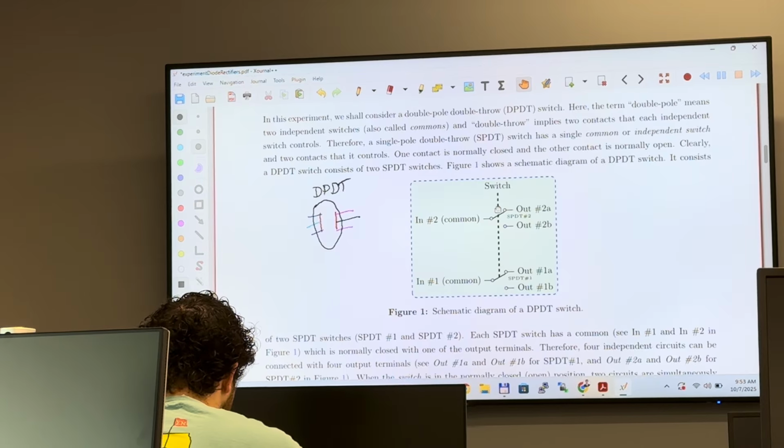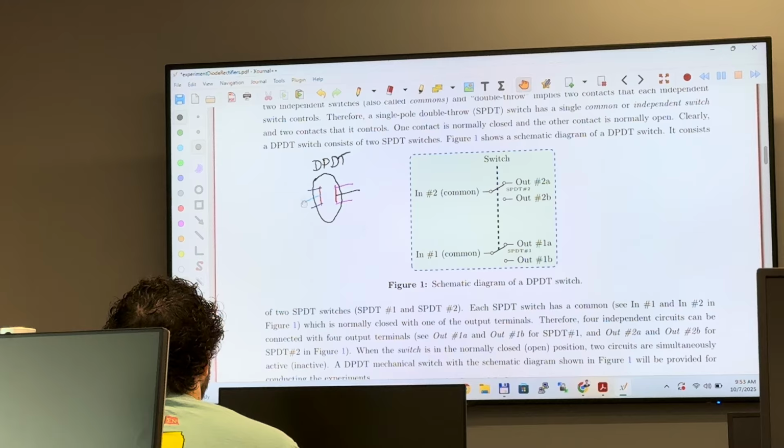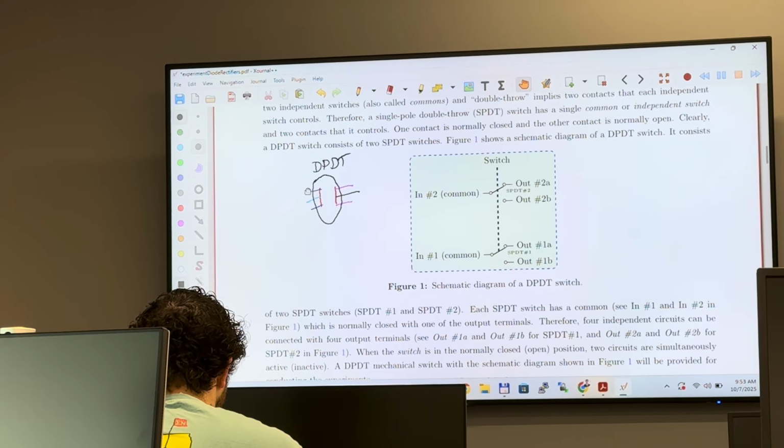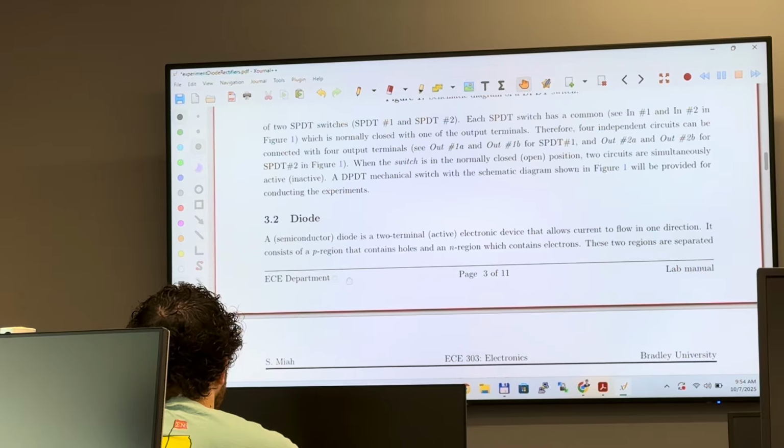You see that? And that's the internal structure of this mechanical switch. So for this side, again, if you have the switch in one direction, this terminal is connected to this wire, or if you switch in the other direction, this wiper is connected to that wire. So it is a double pole, double throw switch, the switch that you'll be using.